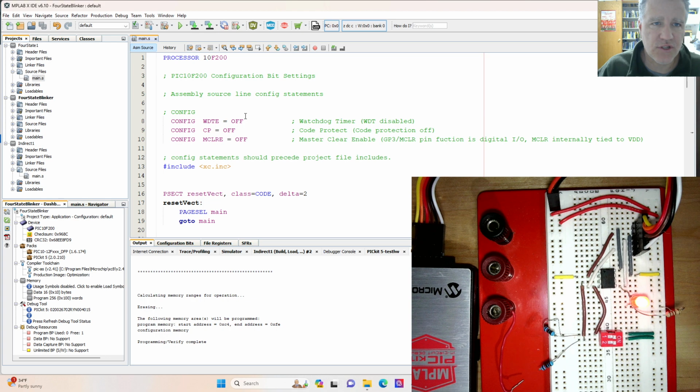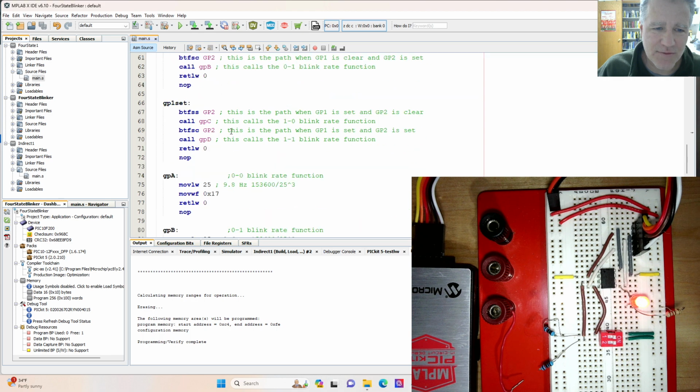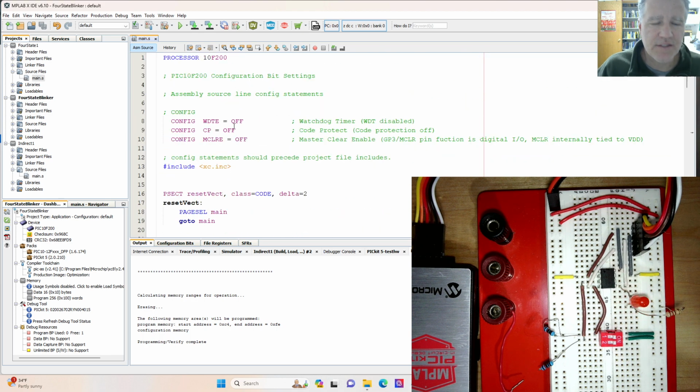Now we want to actually program this, and let me show you something that took me a while to figure out, and this is something that can really throw you. Sometimes the PICkit interferes with itself when trying to write the program, because you have to have the wires connected from the PICkit to the PIC10F200, but you also have that in circuit, and so it really is quite remarkable that you can do this programming in circuit, but sometimes it hangs up.